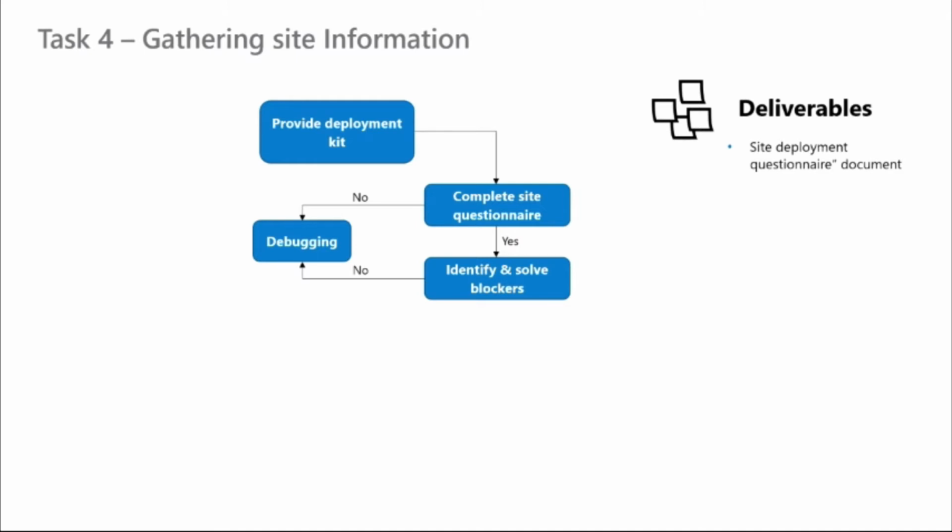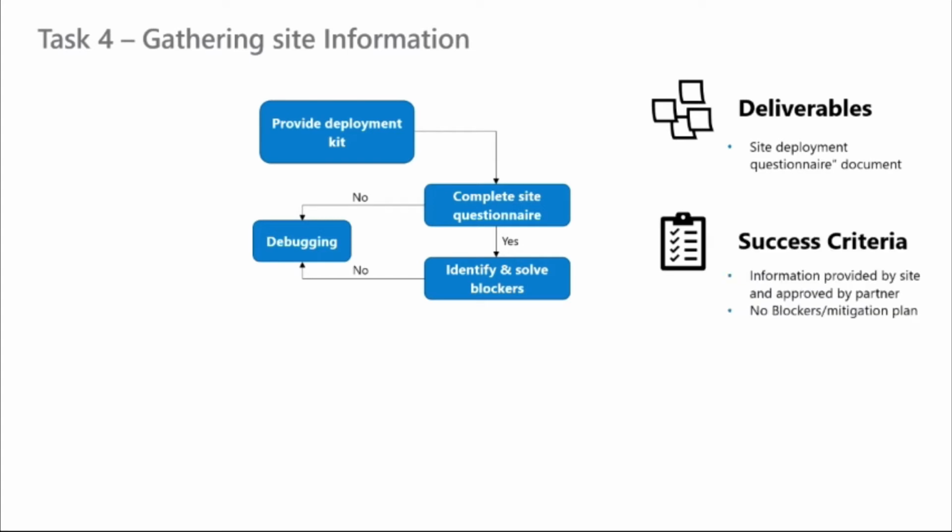Another good tip that I will mention here, and I may discuss it a little later, is about IP addresses that are in ranges that in some methods might be considered public IPs rather than internal IPs. Keep in mind that OT networks, as a hereditary practice, sometimes use their own public IPs in their seclusions because they were confined to work within themselves. So this is something that we might want to consider.